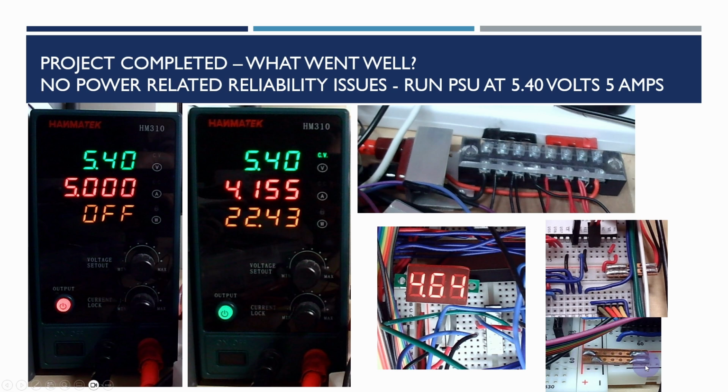And there's also some places where I have to join boards together from the ends where there aren't these sort of lugs, and so I made these sort of connectors again for that. And you can see here, these are the mini voltmeters that I've got located in a number of positions. I tend to put them in the far corner of the board so that you can actually see if there's a voltage problem. Generally, you'll be all right if these are above 4.5 volts.